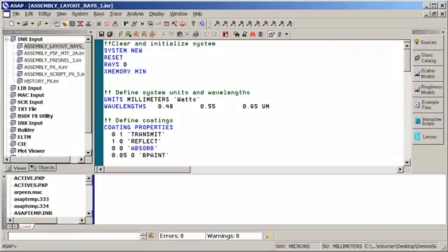We'll also take a look at the effects of obscurations. The general goal is to find out how the light makes it through the optical system. We can use the ASAP Path Explorer to do that. And by going through this analysis, we can make sure that the as-built system is going to meet the design specifications. Now we'll take a look at doing an analysis of an optical system in ASAP.